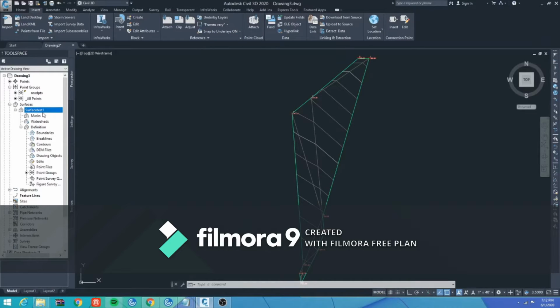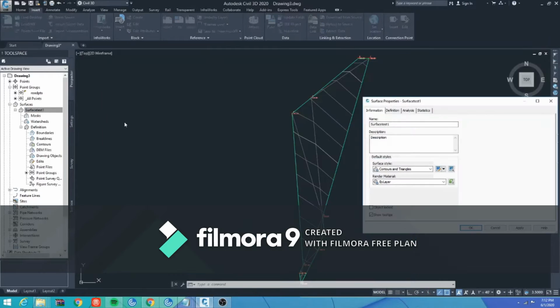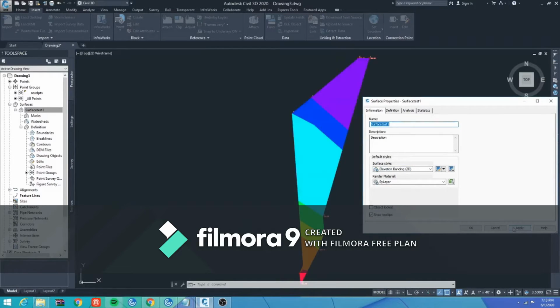We can right click on our surface and go to Surface Properties and change the surface style into what we desire. Let's try this one and see what happens. I'm going to keep elevation banding.